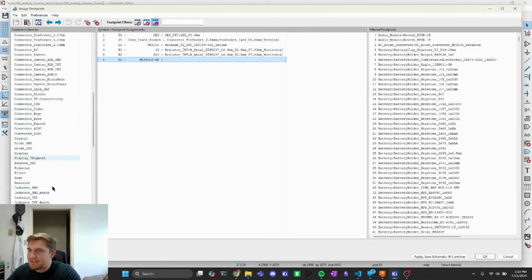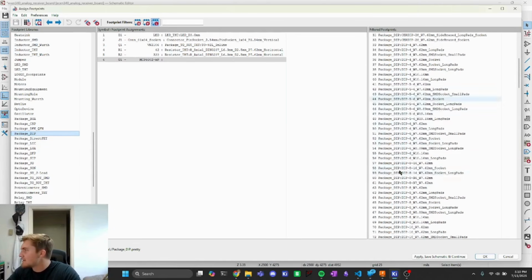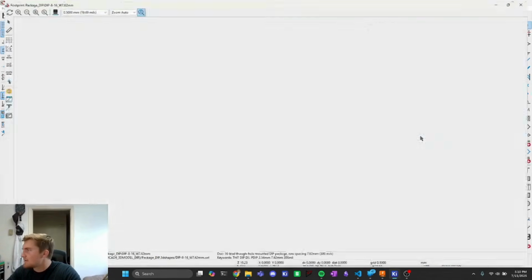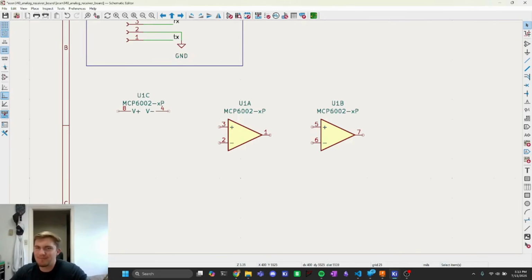We want package DIP, dual inline pins, remember, very nice. We want the dash 8 because we have 8 pins. And I think we just want a simple one. 8-16 should do. Oh, no, that's so long. We don't want that. Not the 16, just the standard. There it is. There's our standard. Alphabetically janky, that's fine, though. Beautiful and perfect. We want them. So 62 here in package DIP, DIP-8 W7. Happy little guy. Let's assign him.